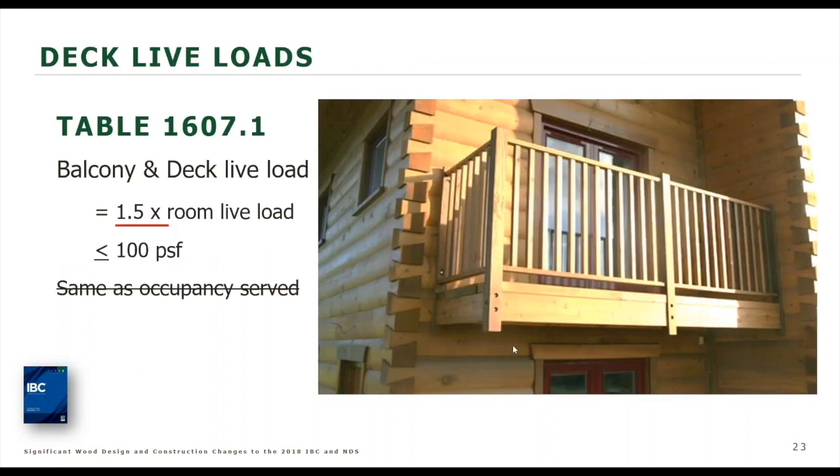Okay, when we're designing buildings, sometimes we'll have balconies or decks out here. This is an example where we have a balcony. What loads do we use when we're determining the structural capacity of our system? Well, as we know, when we're dealing with the IBC and ASCE 7, sometimes they are not in sync when they are being developed. This new change is actually updating the IBC to be the same as the criteria in ASCE 7.